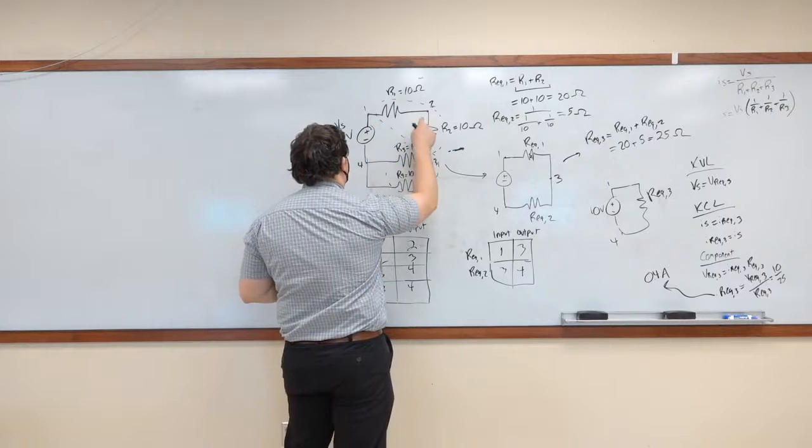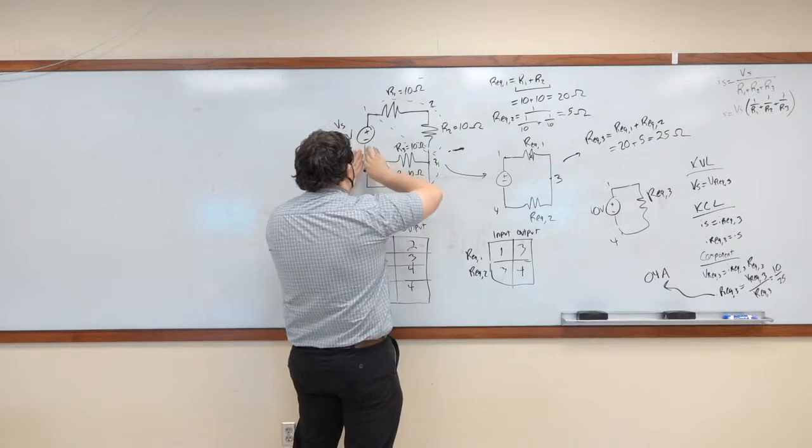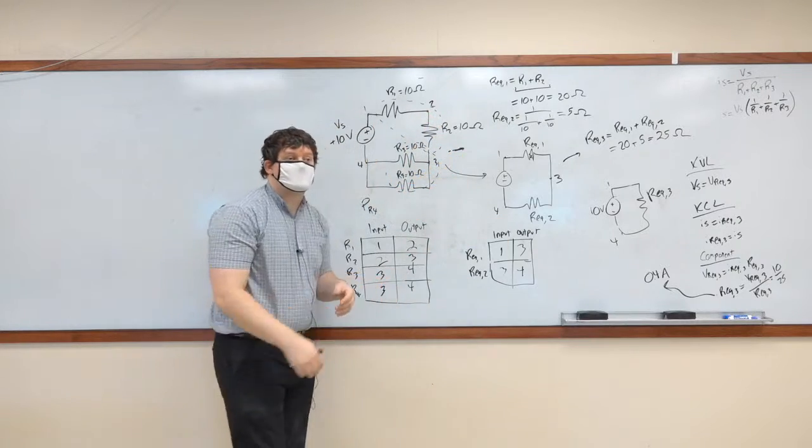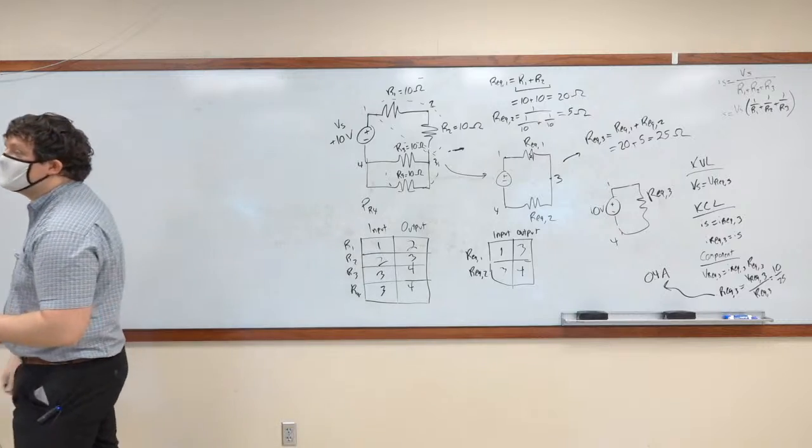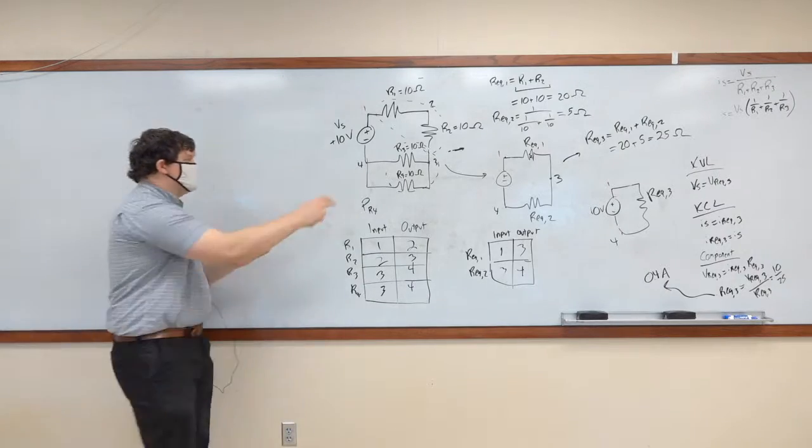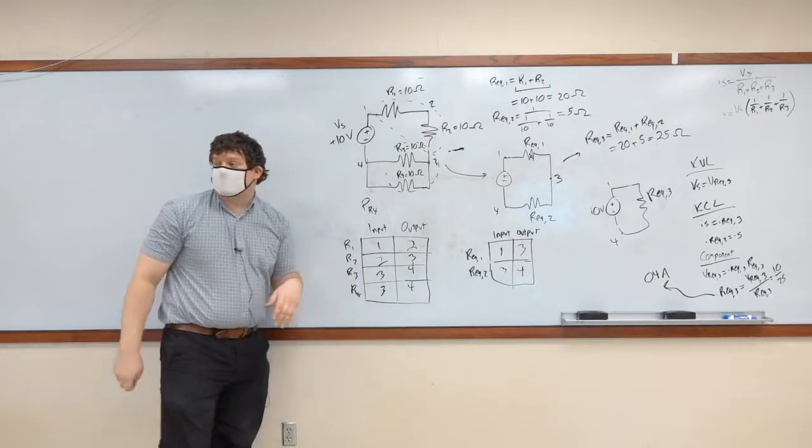There's just one in, one out, one in, one out. So this is all going to be the same. They're all in series. Series components all have the same current. So we know these three are all at 0.4.